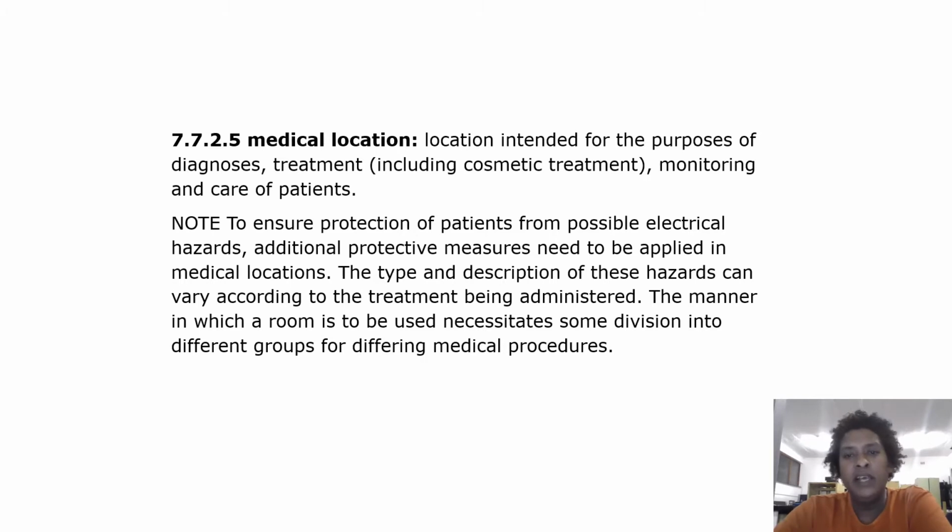Medical location. Location intended for the purposes of diagnosis, treatment including cosmetic treatment, monitoring and care of patients. Note: to ensure protection of patients from possible electrical hazards, additional protective measures need to be applied in medical locations. The type and description of these hazards can vary according to the treatment being administered. The manner in which a room is to be used necessitates some division into different groups for different medical procedures.